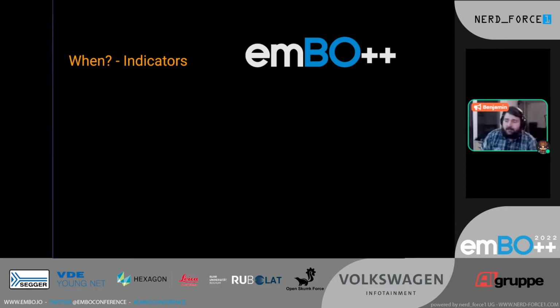So how can we tell where the chip is in this whole process? We can't look at the bootstrap code because it is burned in. We don't know it. It's a black box. But what we can do is observe anything the chip does externally. For example, how much current it draws, or because that is a bit harder to measure, as we would need to put a meter in series with it, instead we are just going to look at the voltage on the pins, because if you increase the current draw, it is going to drop the supply voltage a bit.